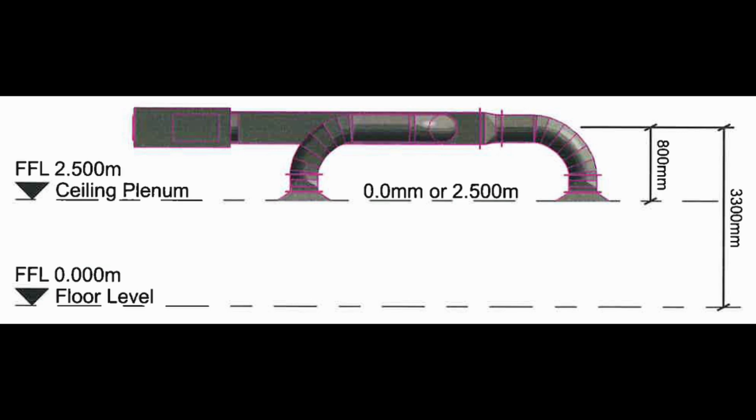Using a dedicated ceiling plenum level can make M.E.P coordination easier, especially when ceilings move. However, contractors may prefer measurements from the actual ceiling, not a theoretical level. The key is early agreement within the project team.